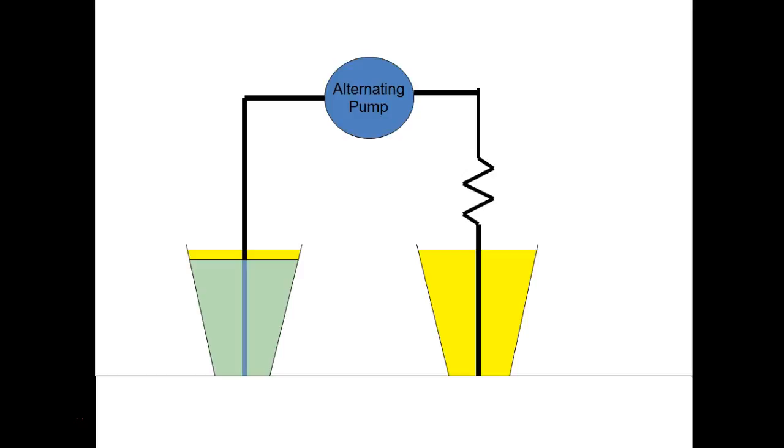When we have full voltage across the capacitor, there's no current flow at all. So that's just the opposite of a resistor, right? It makes sense. The voltage across the capacitor and the current flow into it are 90 degrees out of phase, so it automatically creates a phase shift. Does that make sense?